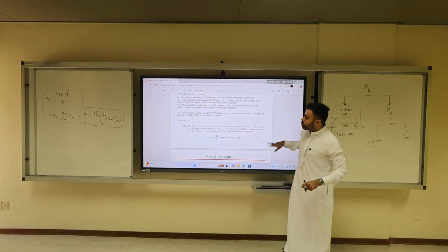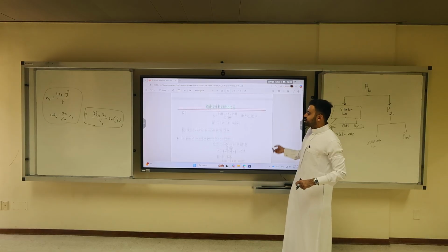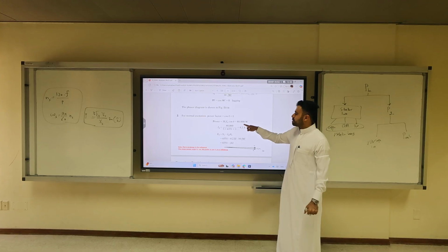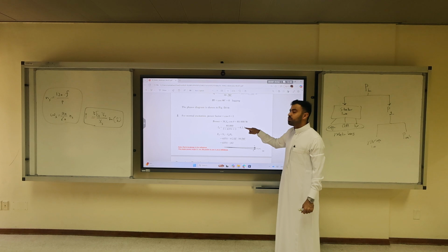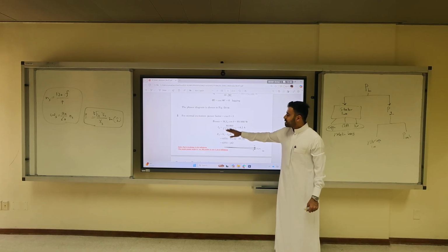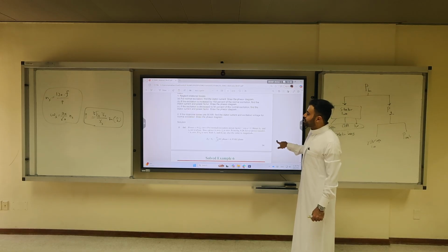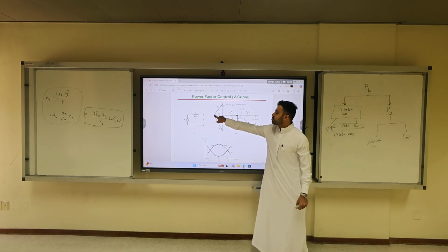But now we equate 80 kilowatts to this quantity, and this is what we do in this part, where we equate 80 kilowatts to 3 VT IA cosine theta, and now I'm getting 4.2 amps, because my power factor is 1, my VT is 6351.3, and this is 80 kilowatts. So in part 1 IA was 0, and in part 2 IA is 4.2.